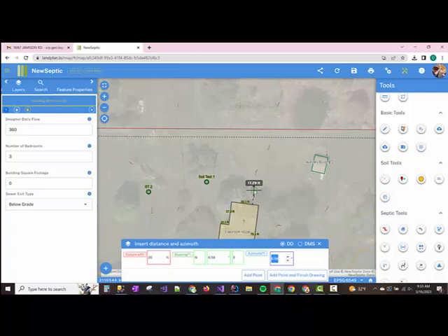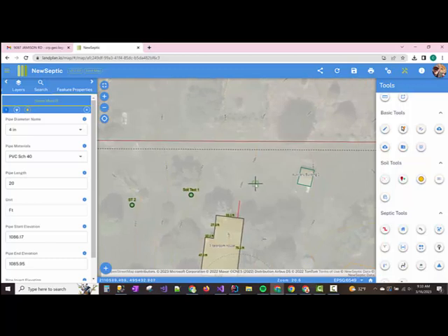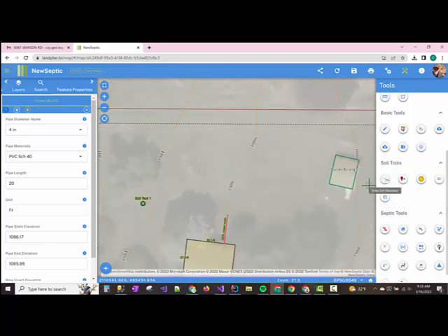So my hand is off the mouse right now. I'm not touching the mouse, and I'm just working on the keyboard. What this form does is you can hold shift and tab and go back, or you can hit tab and go forward. So I typed in my 20, and the azimuth is already set at 6.58. So I'm going to tab over and click add point, or hit the enter key on add point, finish drawing. So now I have my 20-foot sewer main.